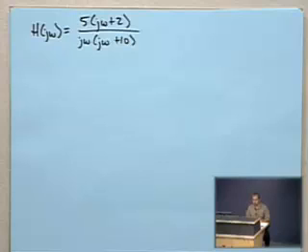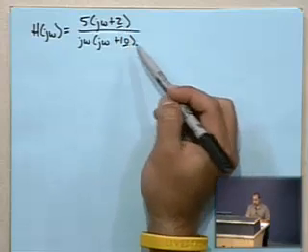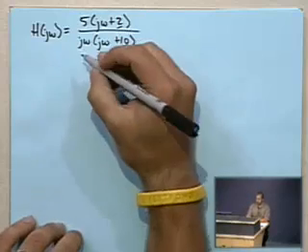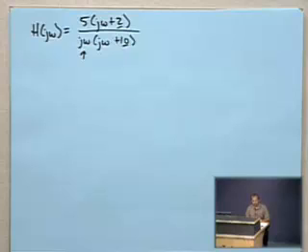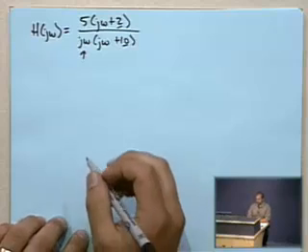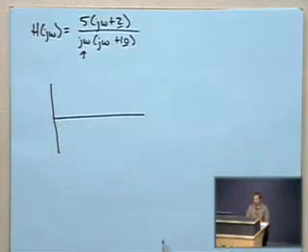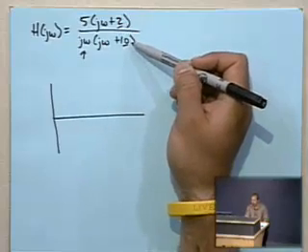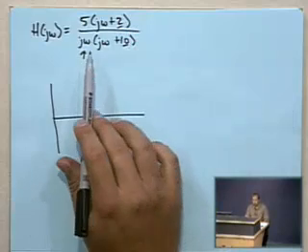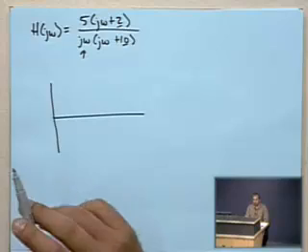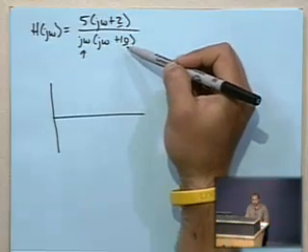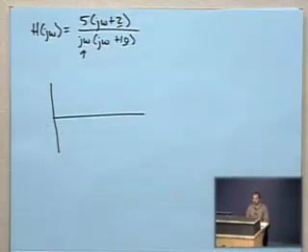But what's nice about this version is that it's very clear to see where the zero and pole frequencies are. But we do have a pole at the origin, and so when we're figuring out exactly where this is going to start, we're going to use this funny analysis technique. What is very clear about the rest of this particular Bode plot is that there will be a zero at 2 radians per second, there will be a pole at 10 radians per second, and there's already a pole here, so basically you're going to see something that's going to decrease for a while, it'll flatten out between 2 and 10 radians per second, and then it'll begin decreasing again after 10 radians per second. That's the general feel of what's going on here.